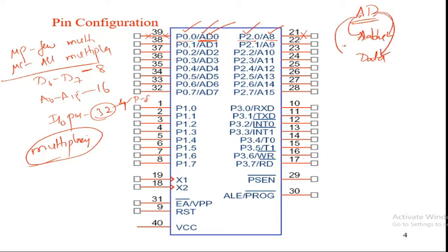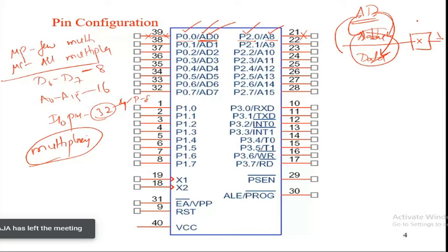So how is this separation maintained? As we transfer the address and data over a multiplexed channel, we take out only one. Multiplexing means we are combining multiple signals and allowing only one. So we multiplex address and data, but allow only one based on the control signal. The control signal that activates this multiplexed bus as an address is the address latch enable, ALE.